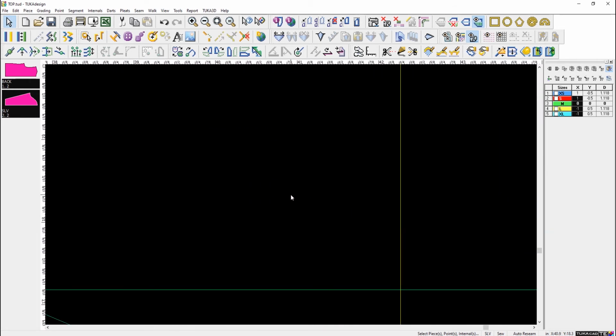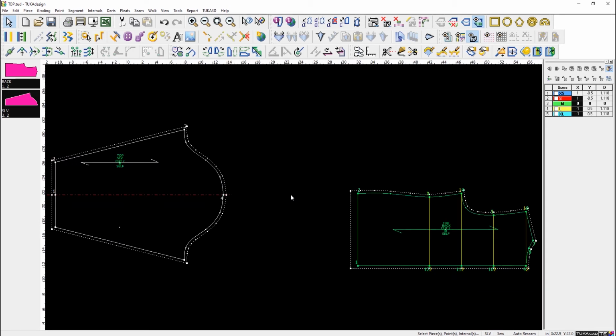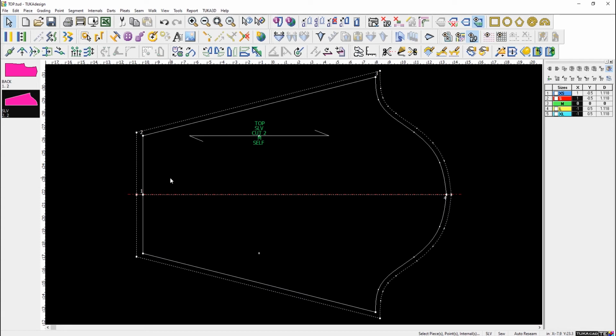And when you zoom in and you want to quickly zoom out, you tap the wheel. So when you tap the wheel, it zooms out to see all the pieces, okay? And that's also on the keyboard, Home. Usually people use the mouse to tap the wheel, okay? If you select and hold the control and tap the wheel, then you should zoom into the selected piece. I'm not sure why it's not doing it for mine. It's because I have group select. Okay, so make sure you deselect the group before you do that.